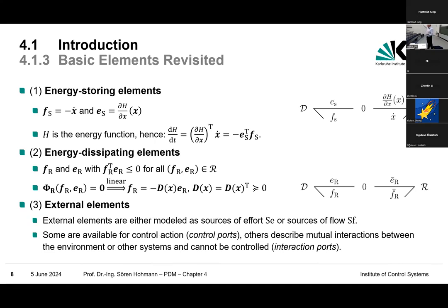So you can look at the inductance, put a gyrator together. So to make it a little bit more explicit, if you have an inductance here, you put a gyrator in between, then this system behaves between these two nodes in a similar way, like a capacitor, and vice versa.